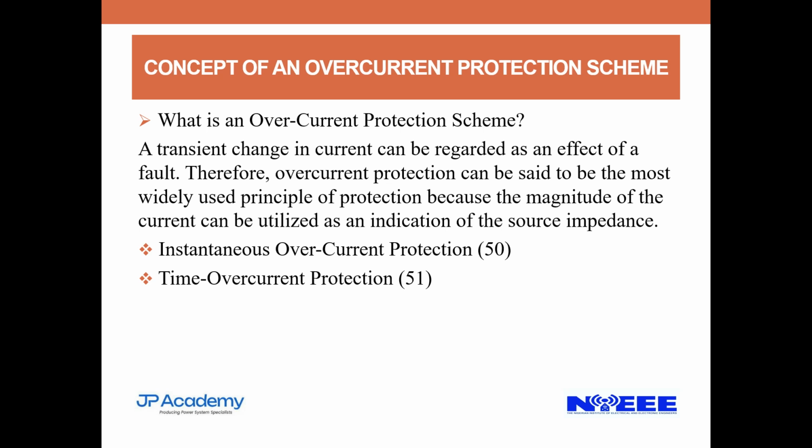Let's say the motor requires 600 amps, a 600 amps motor using a direct online starter, and then we put our instantaneous overcurrent protection. Let's say we say, if the current should get above 1,000 amps, it should trip. It should allow its nominal rated 600 amps.